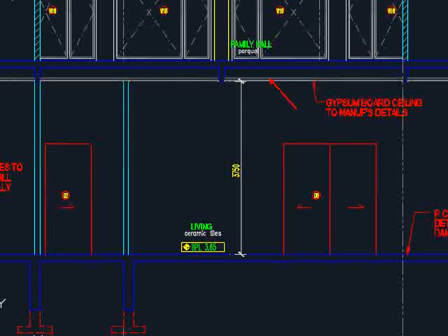This will be the ceilings. The material will be according to the manufacturer's details, but the structural element such as the beam will be designed by engineers. By all means, you should keep your structural element within the allowable space within the ceiling. Unless you cannot fit the size within the space, you will need to seek consent from the architect whether this headroom can be revised.